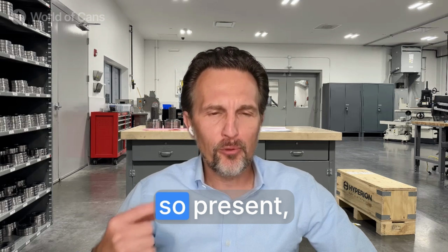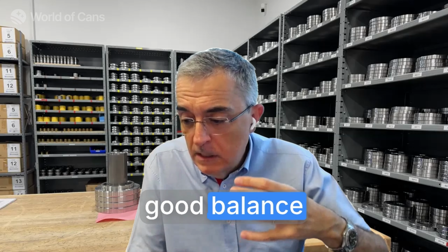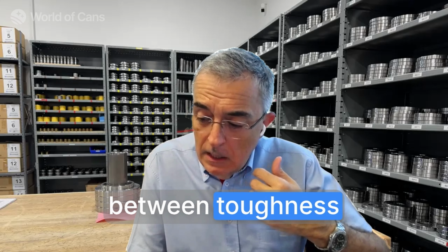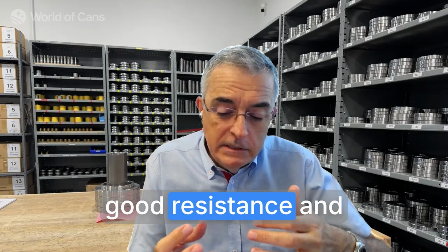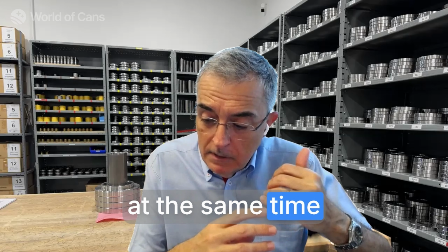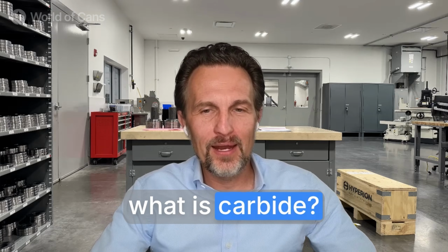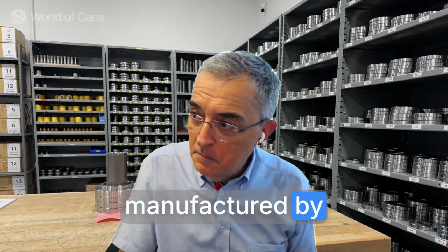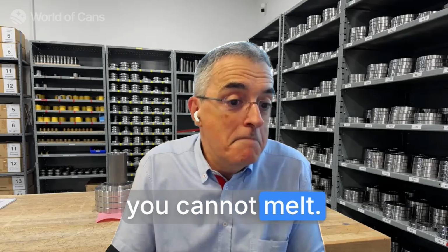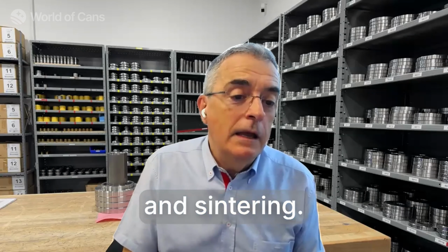Why is carbide so present? Because carbide represents a good balance between toughness and hardness. It's a good balance between getting a good resistance and at the same time having a material that is not breaking. Explain to me, what is carbide? Carbide is a material manufactured by powder metallurgy. It's a material that you cannot melt. You are manufacturing by pressing and sintering.